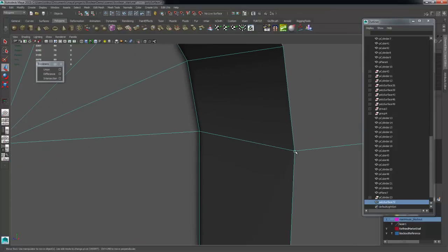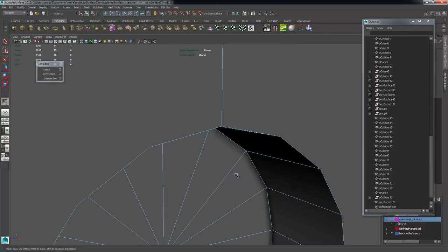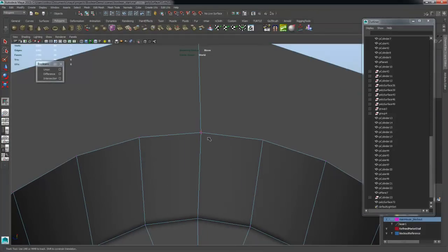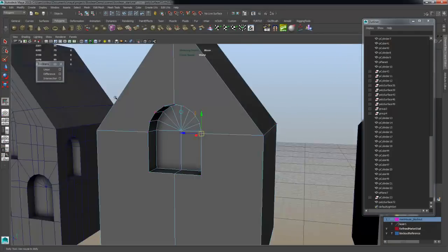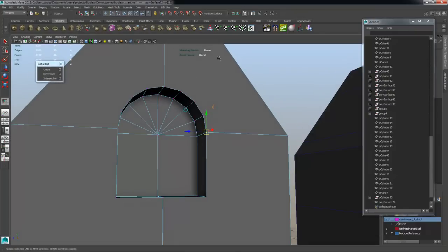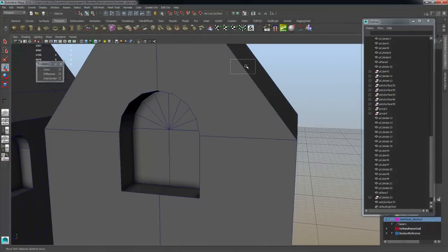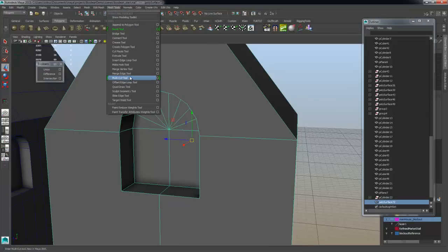And we can actually see that the edges from the original model and the subtraction piece are now connected by a single vertex, since I made sure that they were aligned right off the bat. Once we've done this, now it's essentially cleanup time, where we have to connect these points to the edges, to the outside corners, and we can use the multi-cut again.